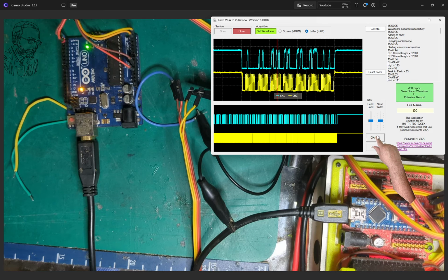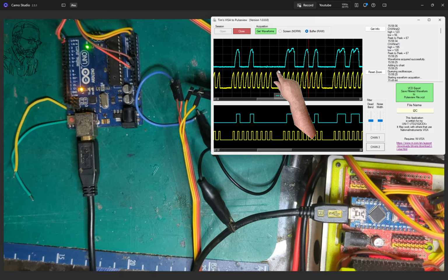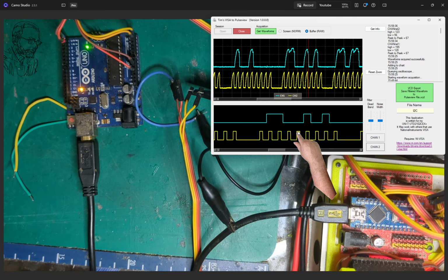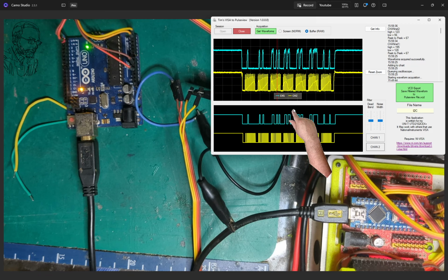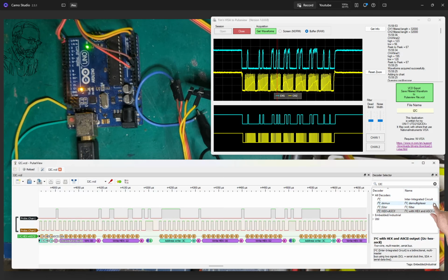We'll filter those two waveforms, and this is what we're actually seeing. This top bit is from my scope, and this is what we've filtered it to. And we're going to the same I2C file, so let's just send it to the I2C file, and then we'll bring PulseView up.